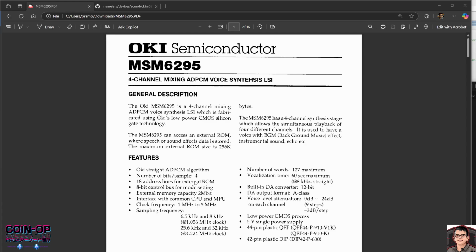You count the number of cycles that elapse at your master clock, and depending on how many cycles have elapsed, you toggle something from high to low and low to high, rising edge, falling edge. That's how you work out timing in an FPGA. So you gate that with a clock enable, and it's synchronized with the master clock, and it will effectively run at that speed.